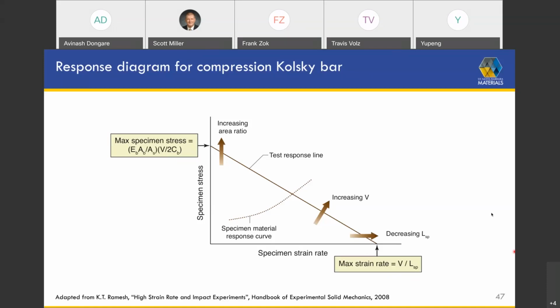Then the stress and strain are calculated from measured strain and the Young's modulus as a prior, and then we get the so-called stress-strain curve. The definition of stress and strain is of course correct, but how can people measure accurately the stress and strain, especially in such a short time, and also the area of the specimen may change a little bit. So could you please comment on that? Thank you.